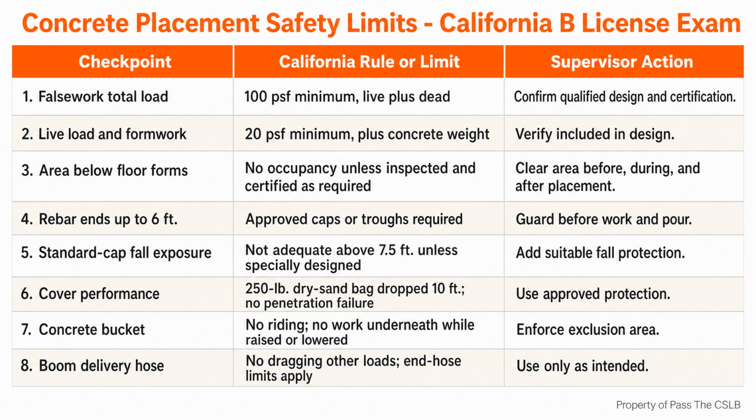During placement, I keep the safety rules as direct as the work. Riding a concrete bucket is prohibited. Employees cannot work under a bucket while it is being elevated or lowered. No hand signal, hard hat, or quick shortcut changes that rule. The clean decision is to keep people out from under the suspended load.